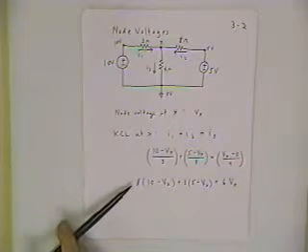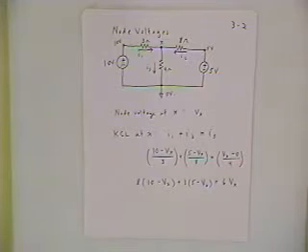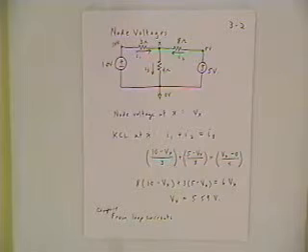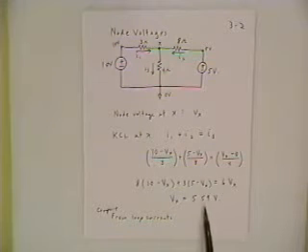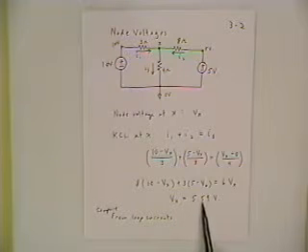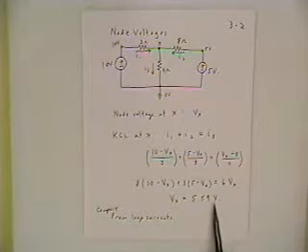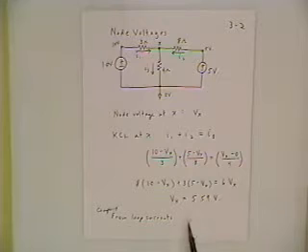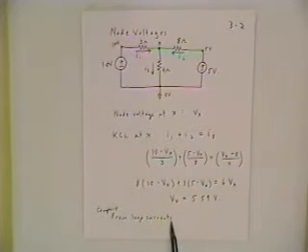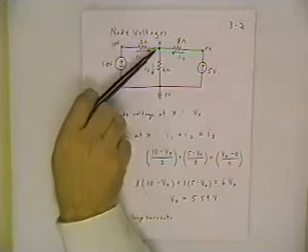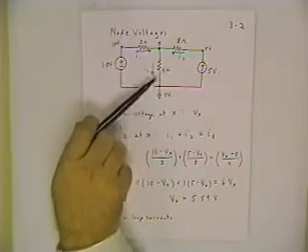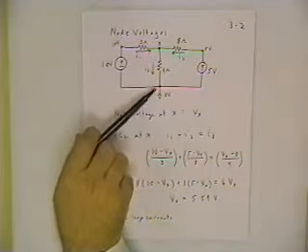So take a minute to solve that equation. We'll resume. Well, I hope all of your equations in your EIT are this easy to solve. V sub x turns out to be 5.59 volts. And now what would be a useful thing to do is compare the result that we got with the loop current technique. V sub x in this circuit is the difference in potential across the 4 ohm resistor.